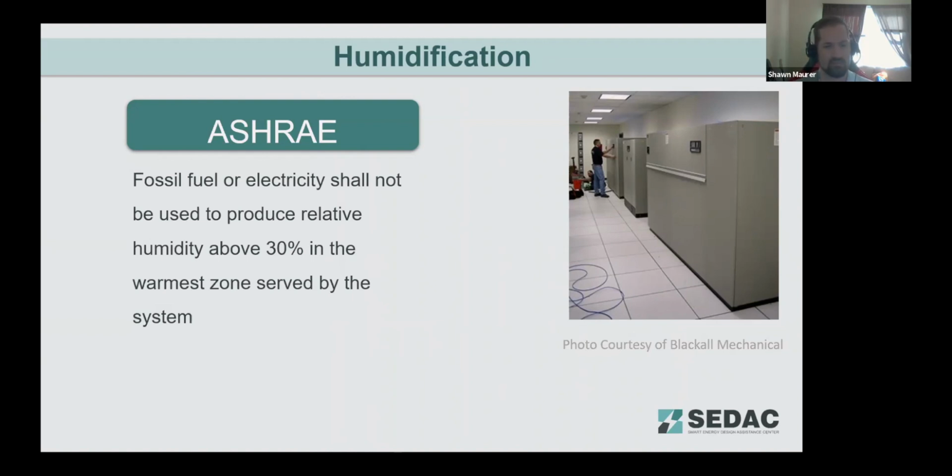That 30% minimum requirement, from studies and other research, optimizes healthy conditions in the building. Again, you're avoiding condensation on surfaces, particularly in the wintertime, and minimizing dust mites and things like that. And so we've got these tight tolerances for dehumidification and humidification to optimize energy performance and avoid any issues they might cause in a building.